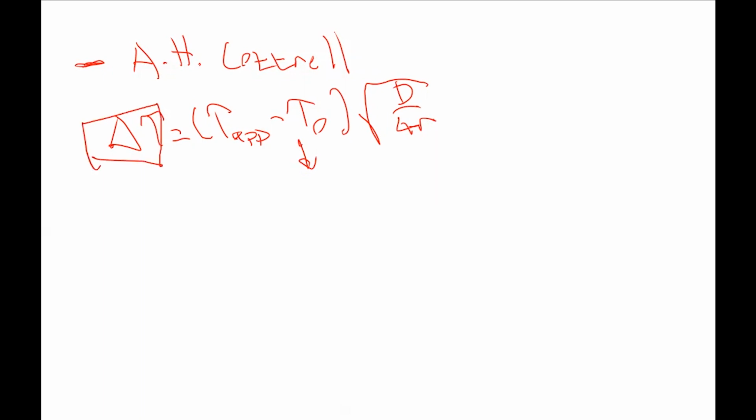This is the stress required to activate the source in the adjacent grain. And we have applied shear stress at which the source becomes active, and tau 0 is just the parallel stress again. And yes, this is another model, but this is just the modification of the Hall-Petch relationship.